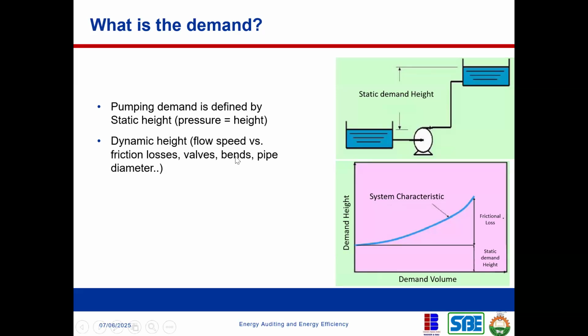If there are bends, I've been to a water processing company industry, and the bends along the flow is just so much, and some of these bends could be avoided. So the thing is that every bend that you have induces loss into the system, because every bend is like a speed reduction, right? So the more bend you're able to avoid, the more you're able to maintain the pressure of the flowing fluid, and the more it can get to its destination, more quickly and in more volumes.